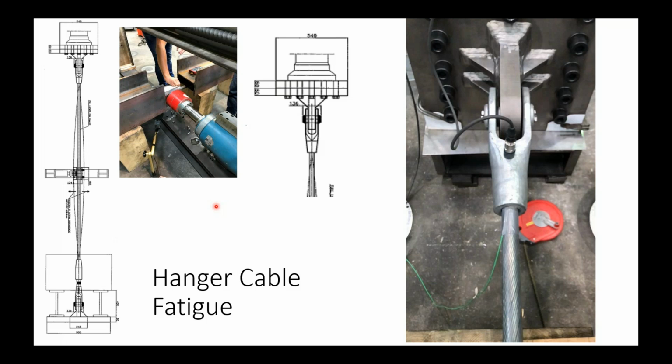We modified our design model to match their erection sequence, and any of the interim stressing loads that they came up with for their modified erection sequence were checked by us in our model. There was definitely a lot of back and forth, not only on geometry control, but stressing, sequence, and constructability. It was a very collaborative method of going, and I think the CMGC process really fostered that collaboration between the parts of the team.